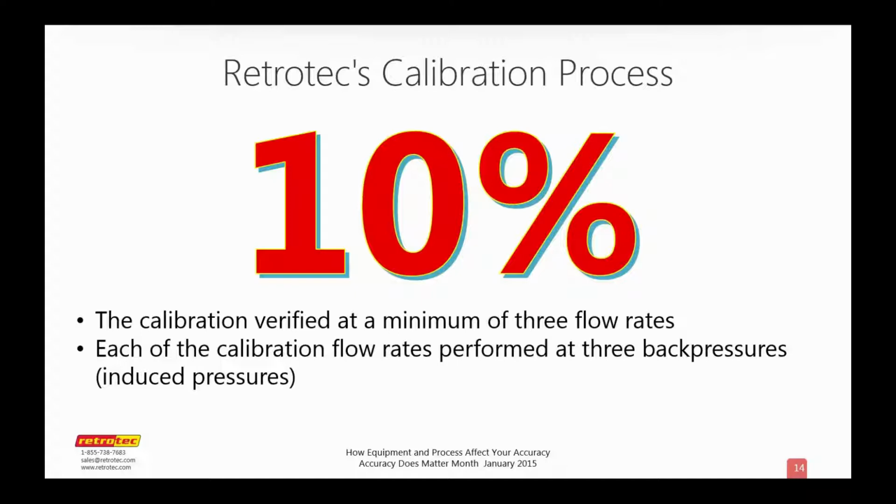So yes, the volumetric flow rate through the holes changes, but because it affects both the holes in the house and the holes in your fan in the same way, our fans are rigged up so they give you the flow that you would get under what we call standard temperature and pressure, which is 68 degrees Fahrenheit and normal barometric pressure. So it's the difference between inside and outside temperatures that has an effect, and it's about 1% difference for about 16 degrees Fahrenheit.